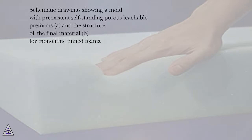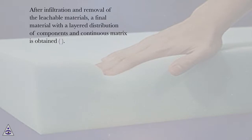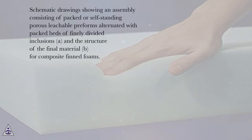Schematic drawings showing a mold with pre-existent self-standing porous leachable preforms, A, and the structure of the final material, B, for monolithic finned foams. Loading of new phases is achieved by building an assembly consisting of packed or self-standing porous leachable preforms alternated with packed beds of the new phases in finely divided form, inclusions. After infiltration and removal of the leachable materials, a final material with a layered distribution of components and continuous matrix is obtained. Schematic drawings showing an assembly consisting of packed or self-standing porous leachable preforms alternated with packed beds of finely divided inclusions, A, and the structure of the final material, B, for composite finned foams.